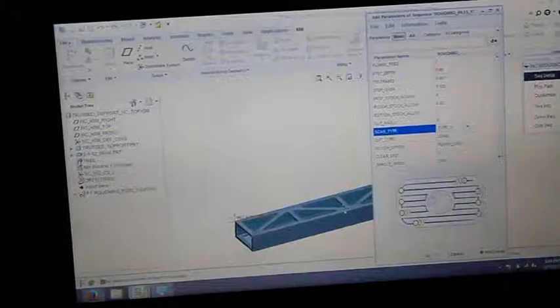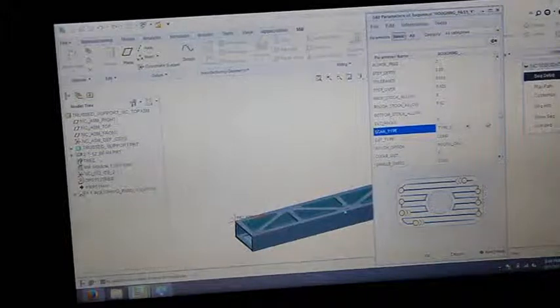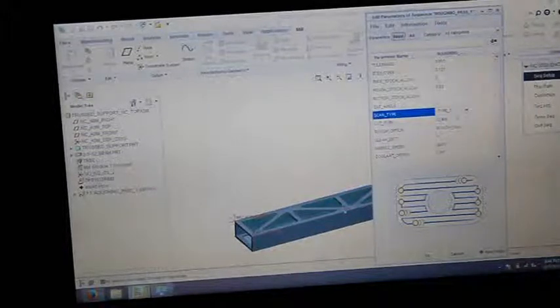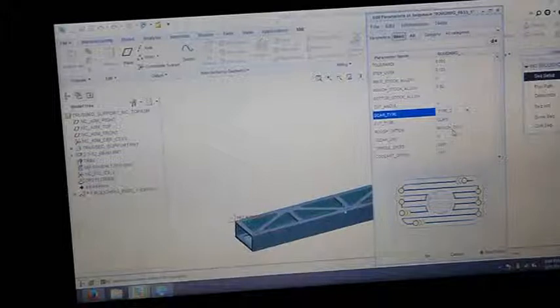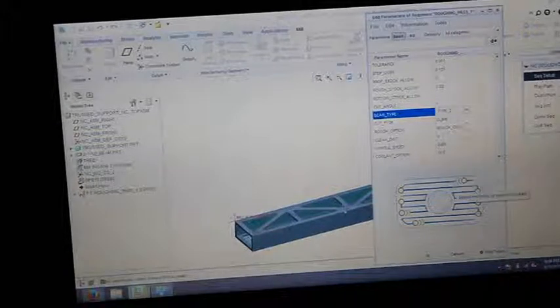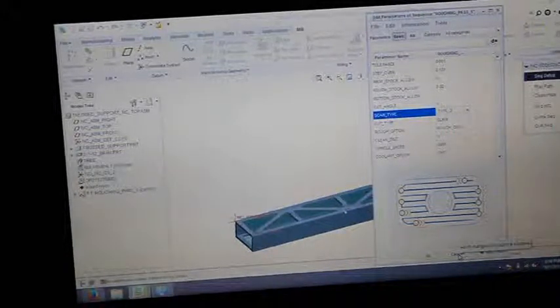Type 3 is our scan type, in which case it's going to run back and forth around the part. There are a number of other options. This just is the most efficient for this type of operation. Climb mill, we're only roughing, we're not doing profile cut, and spindle speed 2000. Spindle speed isn't particularly relevant, but we have it anyways.